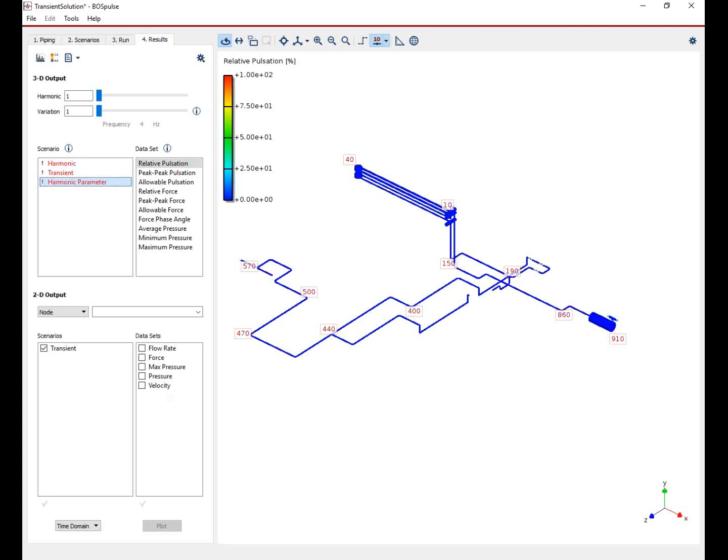If you only have a T-post and you try to restrain the pipe on a T-post, it's very prone to vibrating because the T-post is not stiff. So some triangulation in some cases is even enough to reduce those vibrations. So a lot of different options, and it really depends on at what stage in the design you are and what options are available, also regarding costs.